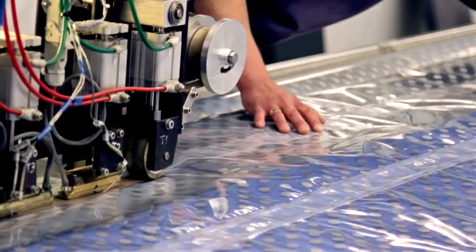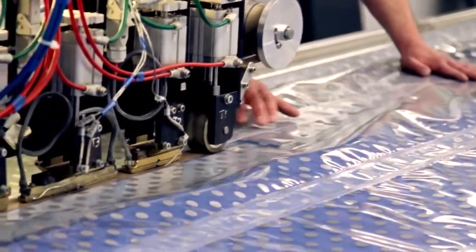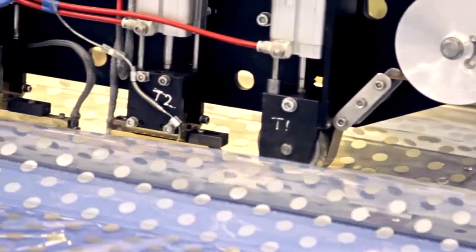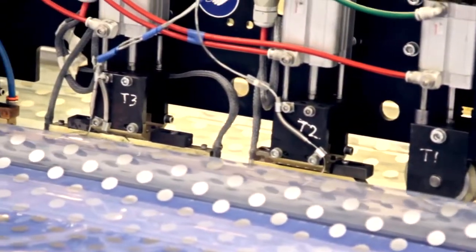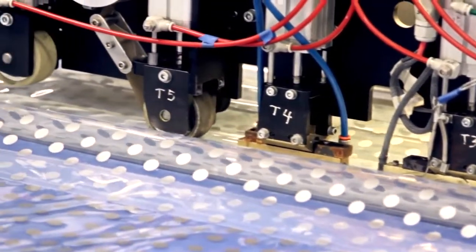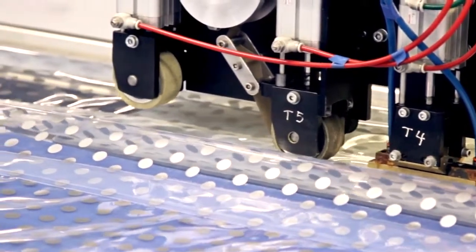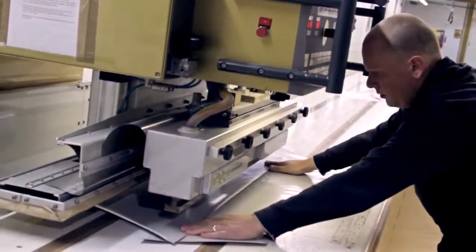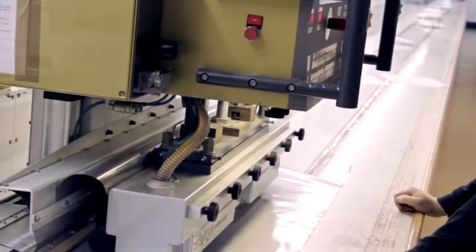Welding works for the majority of our fabrics and is suitable for external use. Some fabrics are joined by radiofrequency welding. This consists of heating the thermoplastic element in the fabric coating using electromagnetic waves to soften them and bond the two layers together. Advanced welding technology allows us to create an even strength across the length of the weld and a bond which will withstand extremely high tensile loads.